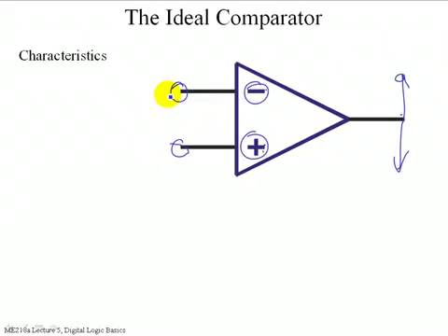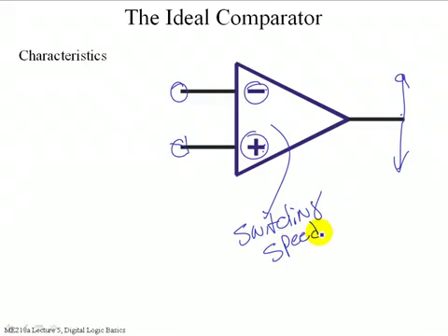And so if it's above, it's going to drive the output all the way up. None of this, if it's a millivolt above, I'm not going to get a gain of 1,000, so 1,000 millivolts on the output. I'm going to drive it all the way to the rail. Technically, if it's a microvolt above, I'm going to drive it all the way to the rail. So internally, this device has been optimized for switching, and in particular focus on switching speed. The result is they've made all sorts of optimizations that lead to a nonlinear response inside the device.